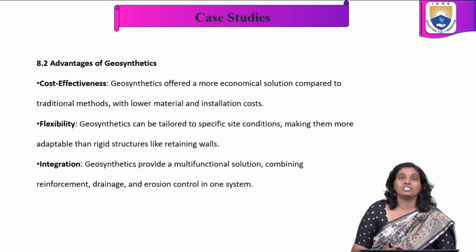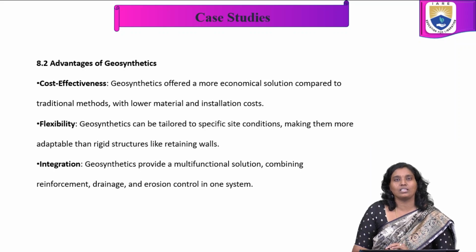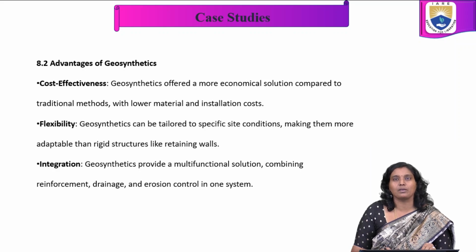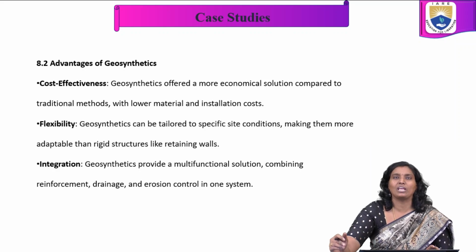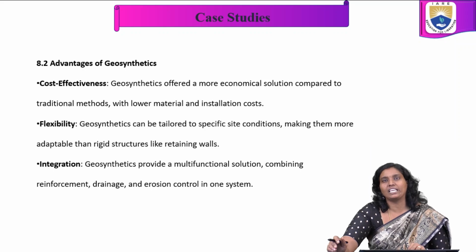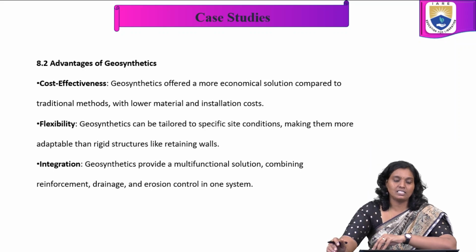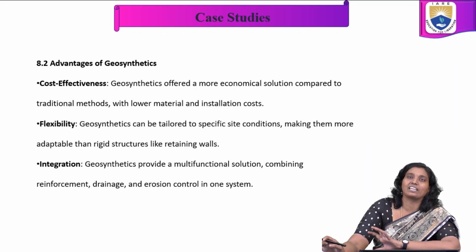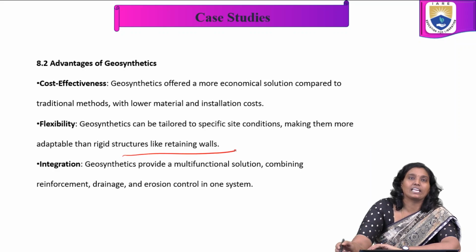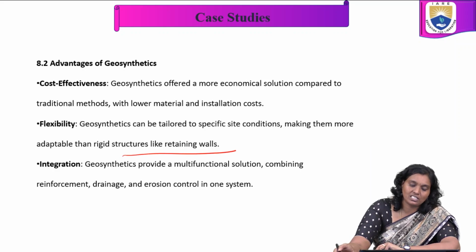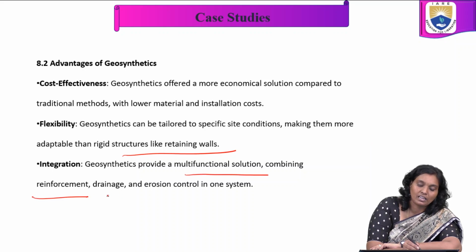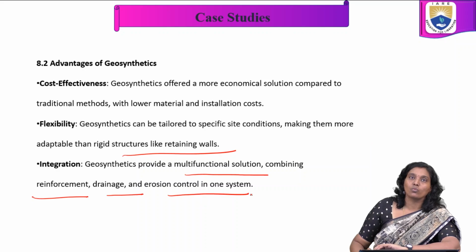In the advantages of geosynthetics: cost effectiveness, flexibility, and integration. Geosynthetics offered a more economical solution when compared to the other traditional methods, with lower material and installation costs. In flexibility, geosynthetics can be tailored to specific site conditions, making them more adaptable than rigid structures like retaining walls. In integration, geosynthetics provide a multifunctional solution combining reinforcement, drainage, and erosion control in one system.